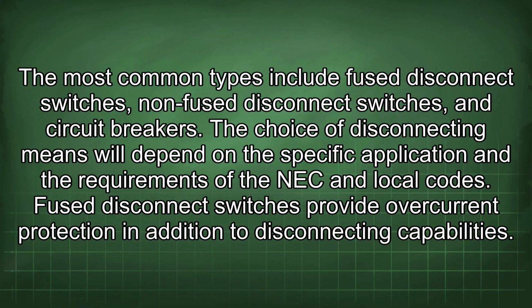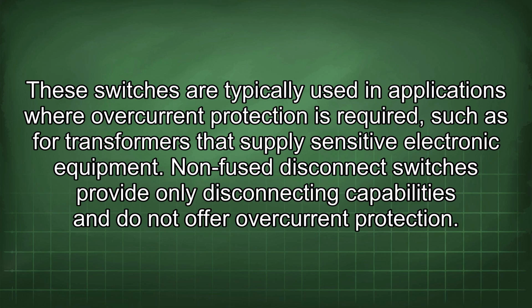Fused disconnect switches provide overcurrent protection in addition to disconnecting capabilities. These switches are typically used in applications where overcurrent protection is required, such as for transformers that supply sensitive electronic equipment. Non-fused disconnect switches provide only disconnecting capabilities and do not offer overcurrent protection.